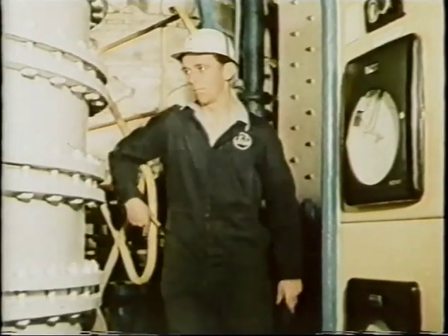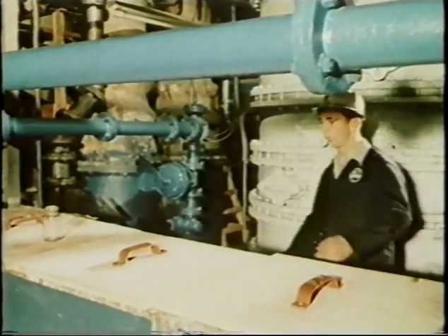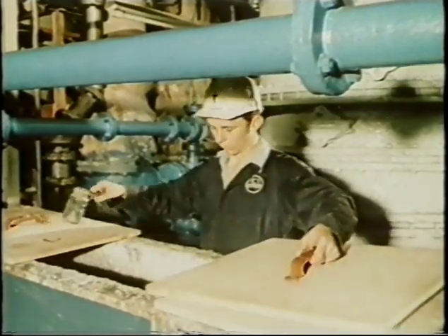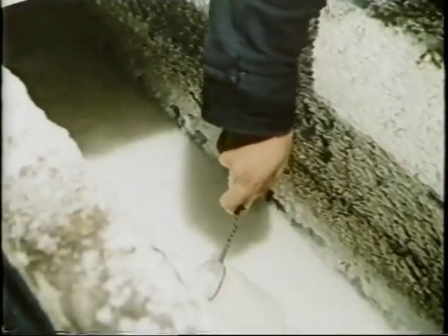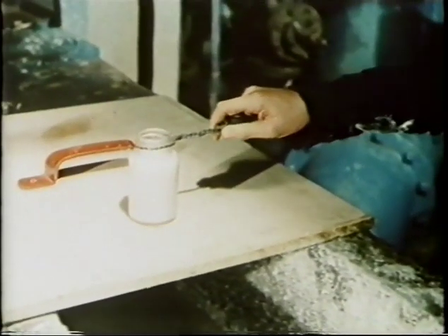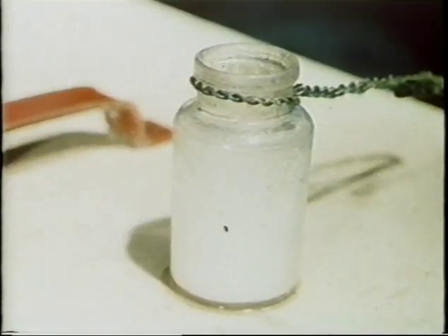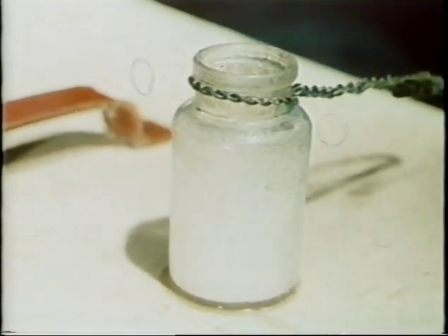Monocarbonation, bicarbonation, precipitation. Such is the pressure of gas in the towers that the suspension is forced up into this trough some 30 feet up from the ground floor. Sodium bicarbonate precipitated in ammonium chloride solution.